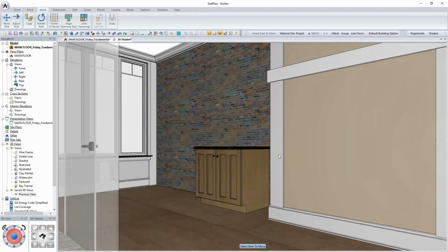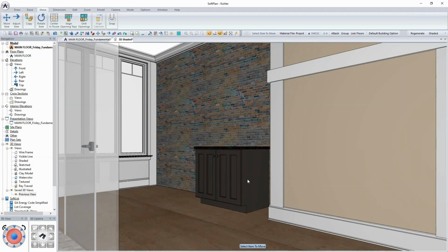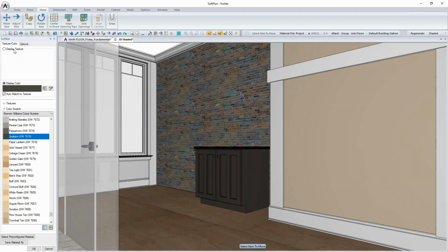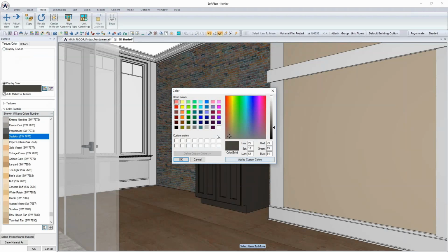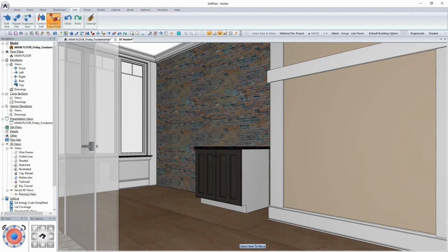And so what you'll see is I get one of these options in there at this time. Now I'm going to begin to edit this. I'll edit this first cabinet right here, and I could change things about it like the finish. By changing it to a painted option, and by default, your paint option may have come in when you edit this, and yours actually shows a simple white color. That's what it's showing here. And then in this case, I'll have the same pattern here. That's what your paint pattern comes in. And all I did, going with more of the grays in here, is just doing a surface edit. So just edit, surface edit.